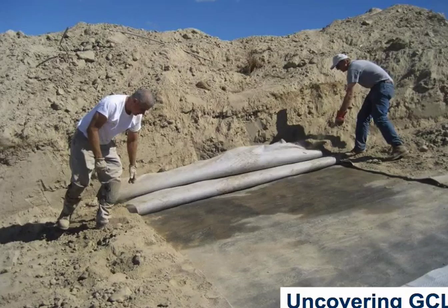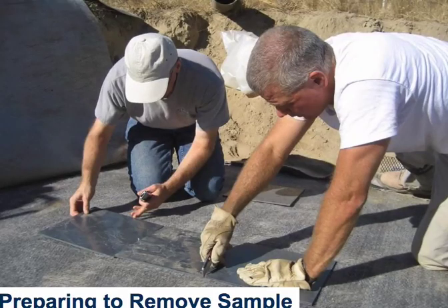Dr. Benson can be seen here working on pulling back a geocomposite drainage layer that was placed over the geomembrane to prevent excess pore water pressures. And you can see that geomembrane exposed. You can see the test pit. And once we expose the geomembrane, we'll pull that back as well, and we'll uncover the geosynthetic clay liner. We'll then take sampling plates and mark out the perimeter of the samples we want to take. And while that GCL is still intact on the subgrade, we'll cut out samples with a sharp razor knife.